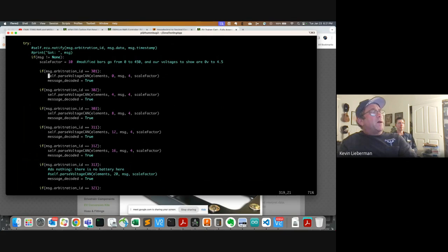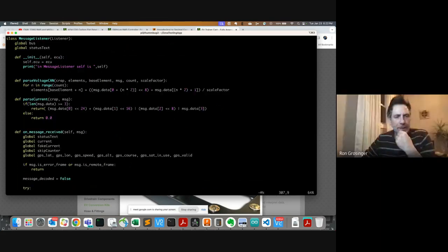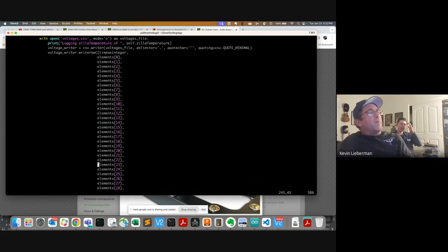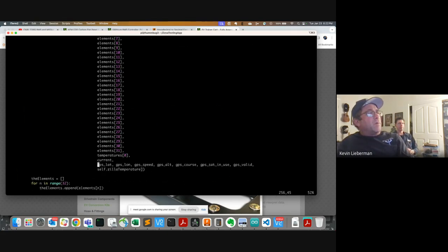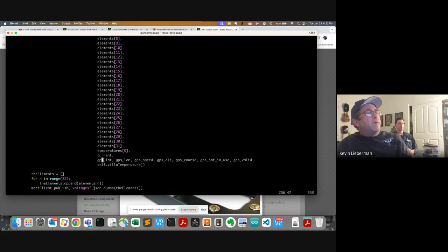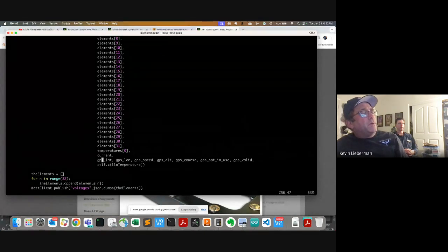Anytime I get any message back, I do some stuff to it. I know that 301, 302, and 303 are all voltage messages, and I wrote a function within here to take that and stick it in its proper voltage slot. Nice. And then from there, I'm making that big CSV file that I was showing before, which is all the voltages, currents, temperatures, everything that I'm getting on CAN, and sticking it into a spreadsheet.